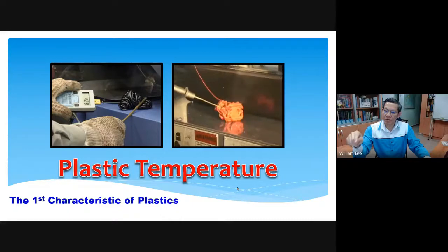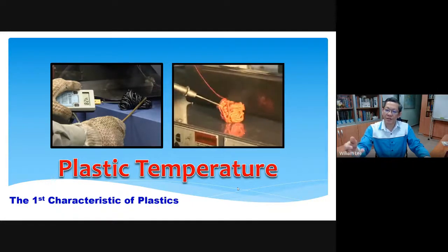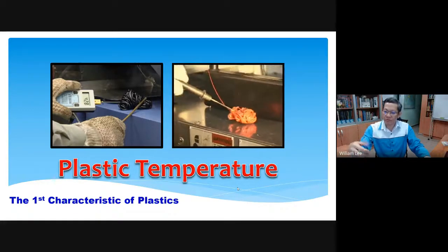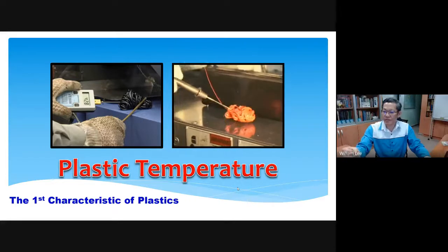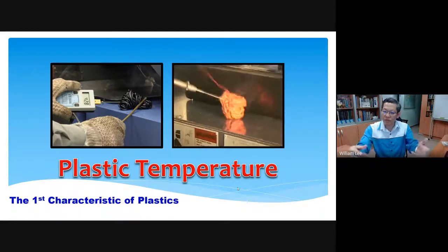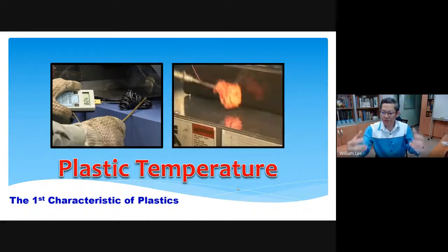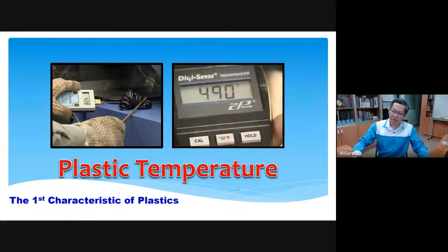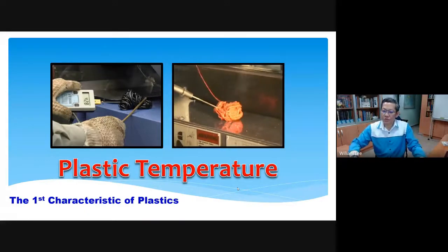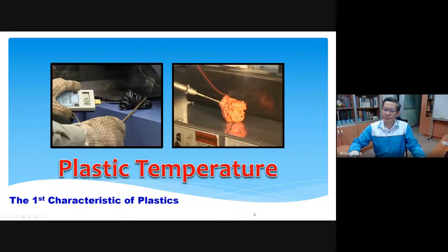So you have to imagine, sometimes when you key in 200, your plastic could be higher heat or lower heat. In order to assure that, you must measure this output information, right? Because after all, at the end of the day, what you are trying to process is a material. Material must receive the required specification, right? So plastic temperature is one of the important characteristics here.